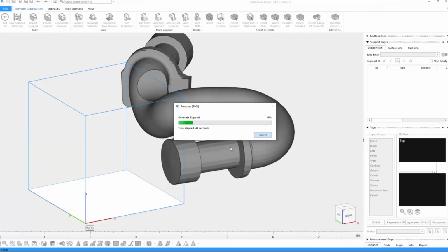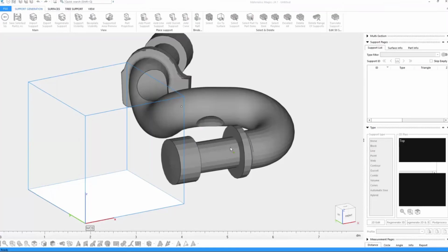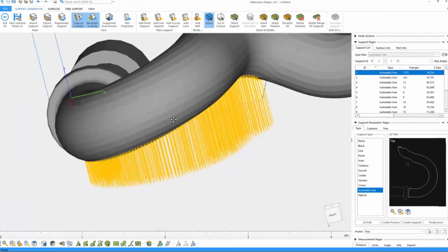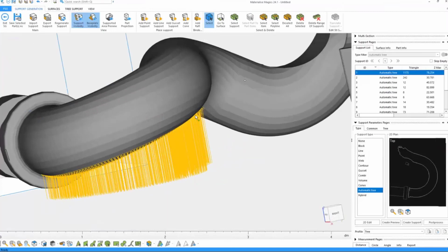Again, sorry, I believe WebEx is. Did we have any other questions, Jeremy? Yeah, there's actually a few questions. I was trying to keep them to pertain to what you're working on. One of them is in regards to the pins and holes, the alignment thing that you were doing with the pins. Is there the ability to adjust the tolerances on those? Some orientations you might need a different tolerance, or even some materials might require different tolerances. Do they give you the control to change those? Yes, absolutely. You have control over the size of the pins, spacings, what kind of gap you leave between the pins, so if you're trying to leave room between the two parts for epoxy or other bonding method. And you can even control the mesh resolution for those pins that are generated. That will determine how your cylinder is truncated by the triangular mesh.